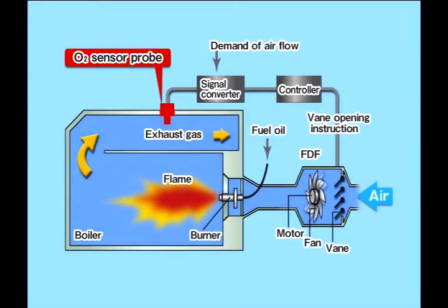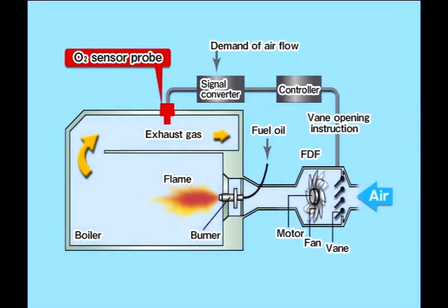The oxygen analyzer is an instrument used to measure combustion within the boiler. The boiler uses a forced draft fan, or FDF, to intake air for combustion. When FDF ventilation is reduced, incomplete fuel combustion occurs in the boiler, generating a large amount of dark smoke. Conversely, when ventilation exceeds recommended limits, heat loss occurs.